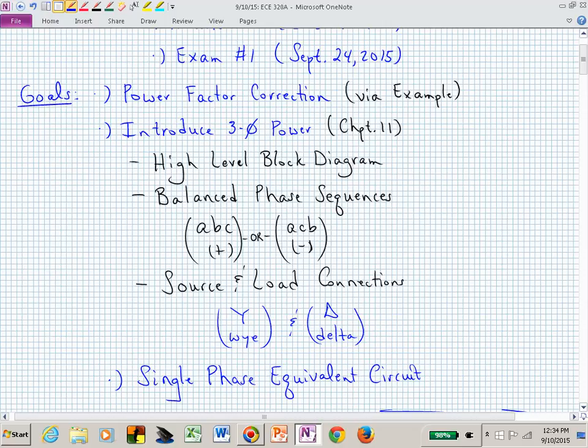If you had to cut a pie in three, and it's not 3.1415, it's not that pie, it's like a cherry pie or an apple pie. If you now have a pie, and now I'm really hungry, how do you cut it equally into three pieces? Well, you would be cutting at an angle of 120 degrees. And that's really what's separating each of these phases, A, B, and C, in this three-phase power system.